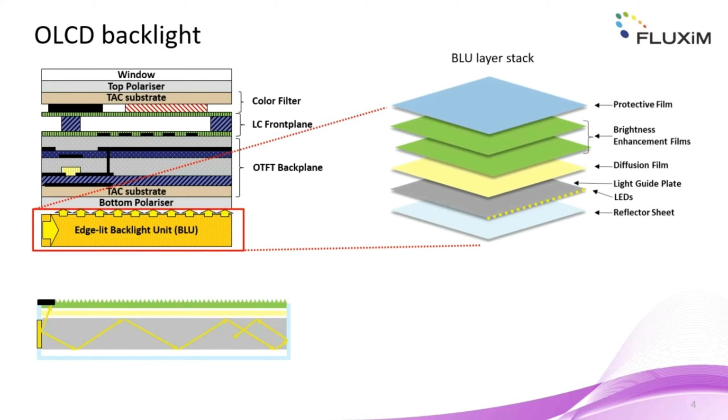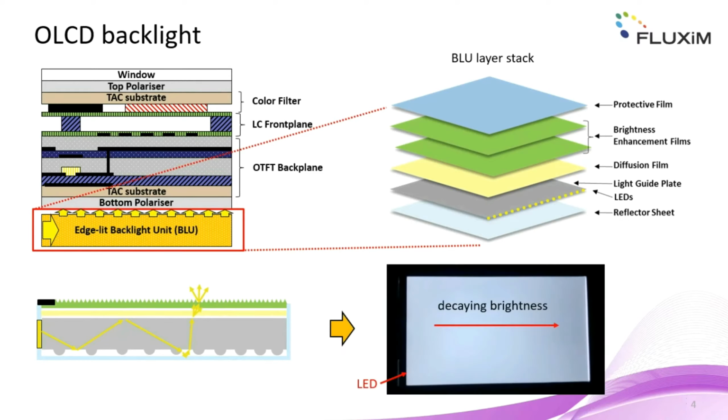The light guide plate itself enables the directed propagation of the light via total internal reflection. However, to couple out the light uniformly, some bottom roughness features are required, whose density increases with the distance from the LED to compensate for the decreasing amount of light left in the light guide. The beams are then widened and redirected by the actions of diffuser and brightness enhancement elements. The main challenge in the design of a standard flat backlight unit is to achieve uniform outcoupling at the top surface in terms of both spatial intensity distribution and angular characteristics in spite of the edge illumination.